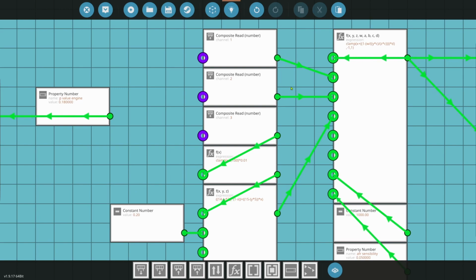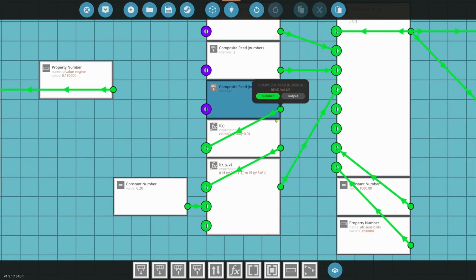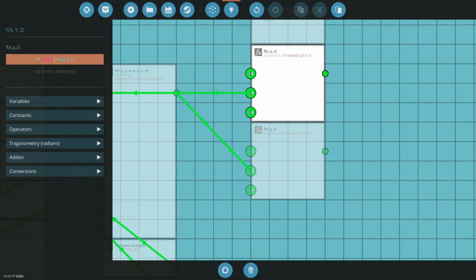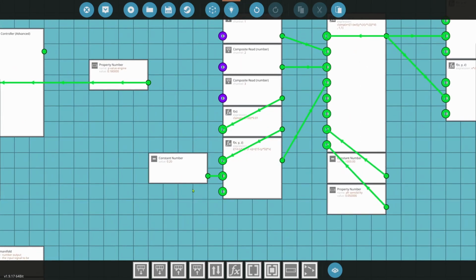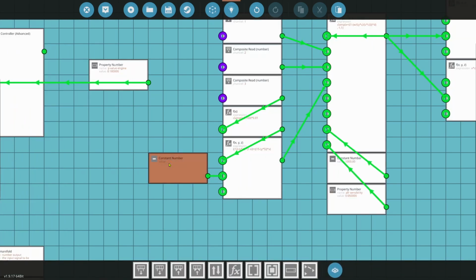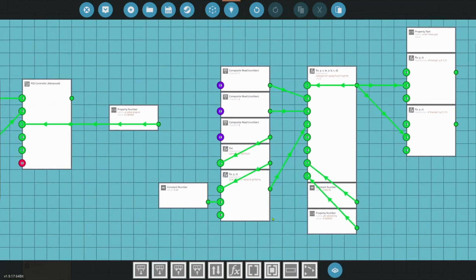Stoichiometry, essentially for our cases, is the air-fuel mixture that allows our engine to run at the setting that we are putting it at. So those go in here, and then they are read out, and we go into here and we get a clamp. We have 1 minus y, 0.11. We don't really need to worry about this too much. You can copy this. This works well. This is our AFR. Our desired air-fuel ratio is 0.2. You can change this. This is where you would change it, right here.